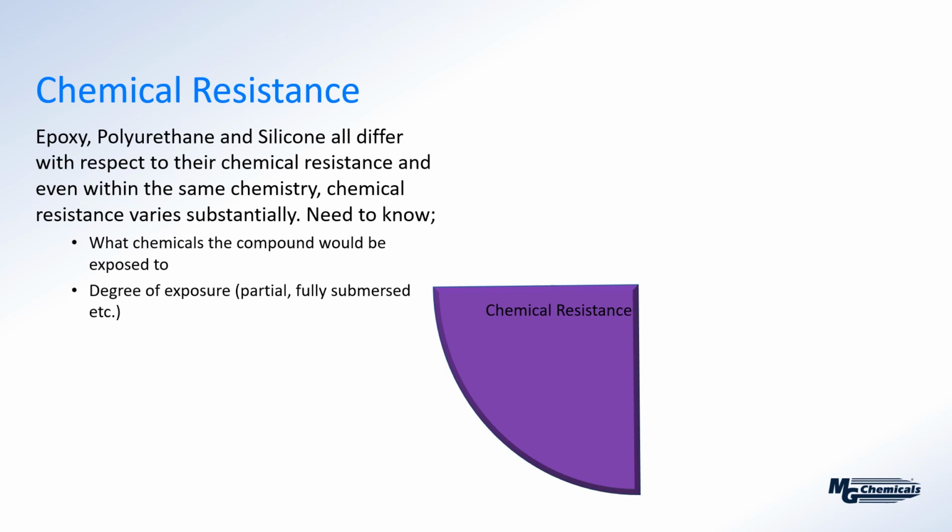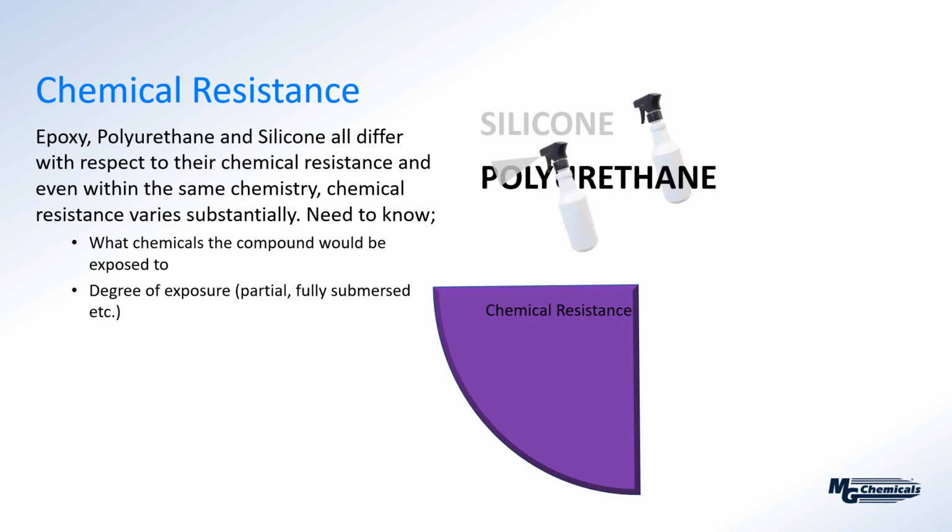So then let's basically do this and summarize how these different chemistries distinguish themselves. So let's take silicone, for example, and let's say we have a standard solvent. We'll say it's acetone. We immerse it in the solvent and we see a certain degree of fading based on the exposure. Now let's compare it to a polyurethane. Again, the same chemistry, an acetone, and it will fade somewhat, but in general, it's going to hold up better than will the silicone.